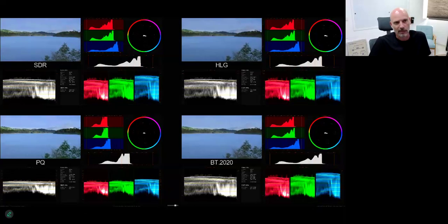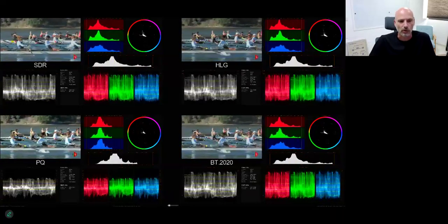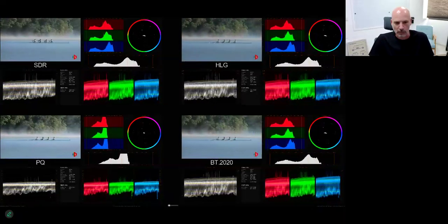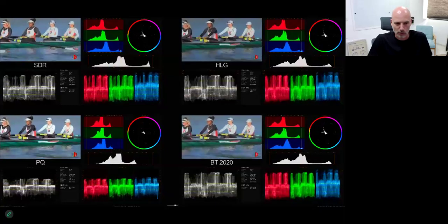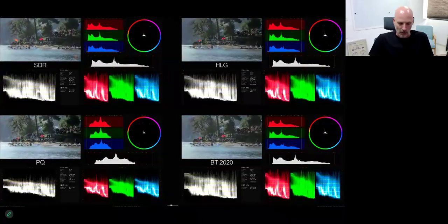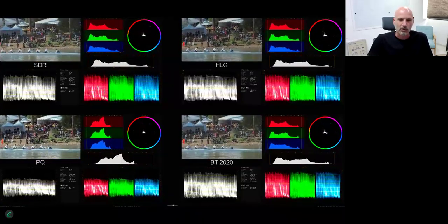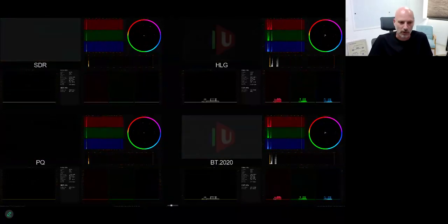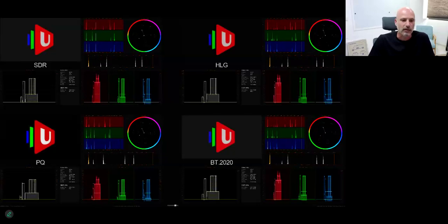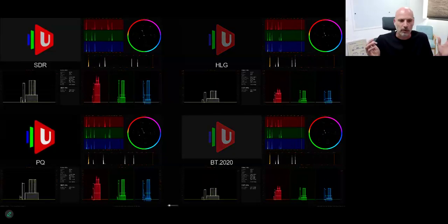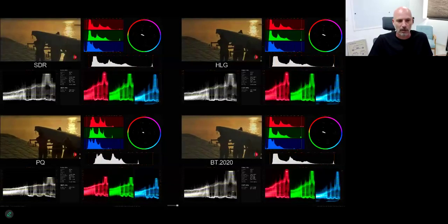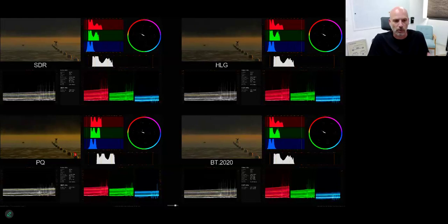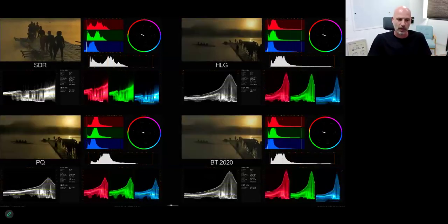So a very basic LUT is just the LUT that the screen will use in order to convert the YUVs that it receives on the stream into the RGB values that it needs to push to the pixels. Now, a more sophisticated LUT converts RGB to RGB, meaning you're taking something and converting it into different colors. The equation of the LUT can do everything. You can invert colors. You can do all kinds of things. It's not just tuning the colors. You can do whatever you want in the mathematics of the LUT.